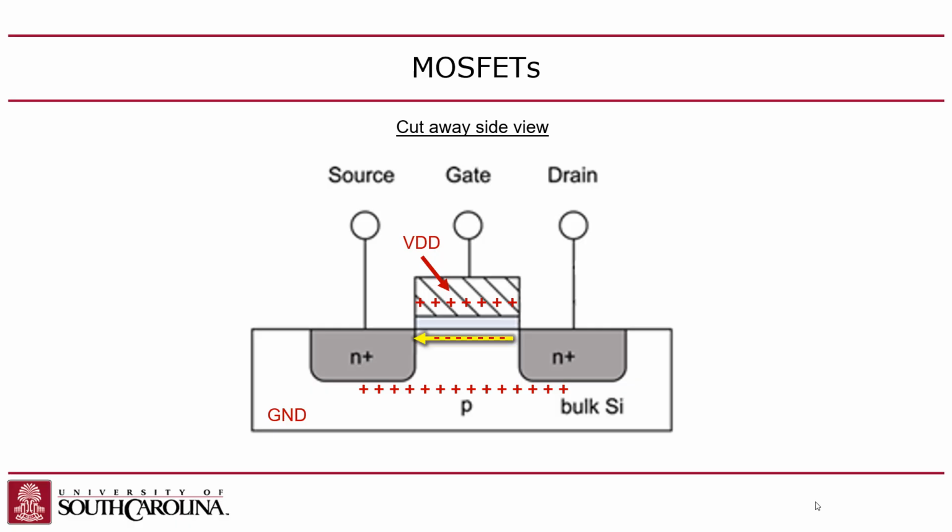So in this case, this is called an NMOS. Why is it called an NMOS? There's P and N, right? Because the source and the drain is the N. So the transistor is named after the dopant used for the source and drain, right? You don't name it after the dopant that's the body, which is the substrate, which is the channel, right? Okay, so that's an N-type.